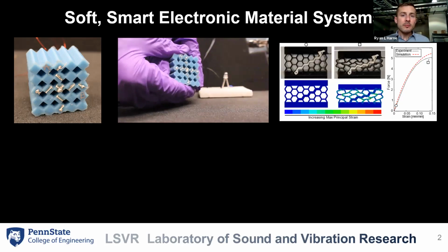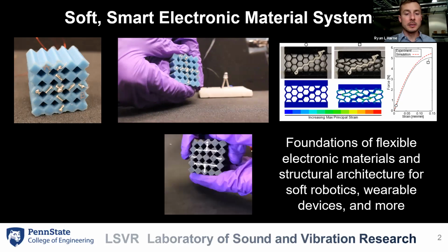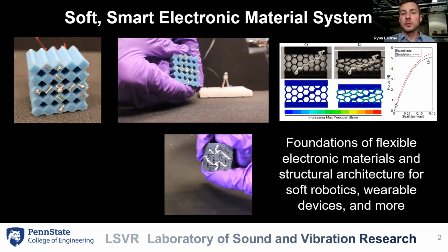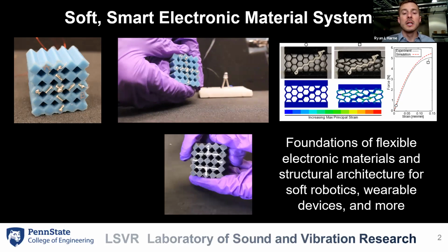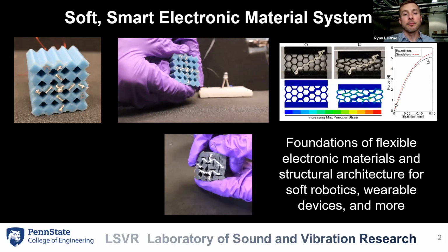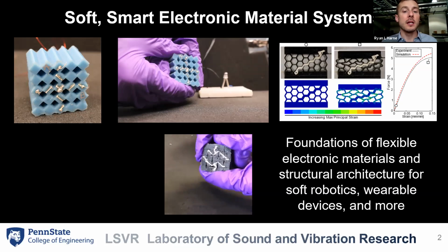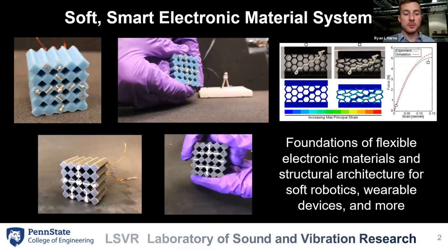We've studied the behavior of this type of trace for a wide variety of systems to understand both the mechanical behavior as well as the electrical behavior. Through all of these efforts, we're creating this foundation of understanding how to use flexible electronic materials for sensory as well as decision-making capability. Some of the digital switches that we're investigating so far involve literal logic gates constructed on the basis of the combination of the silver TPU network as well as the geometry of the substrate.